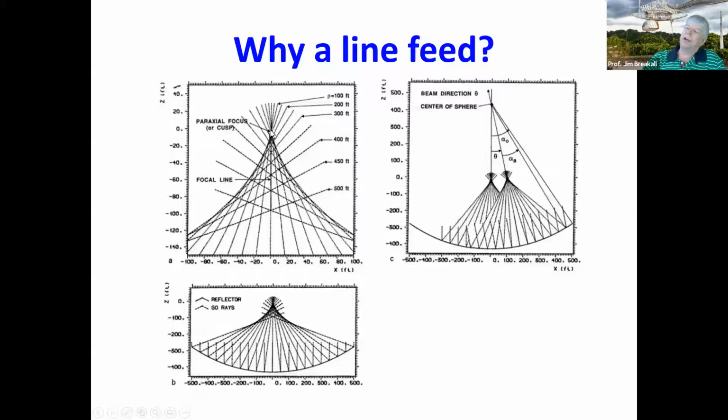So if we could put an antenna from this point down here, we could then collect all those rays, but they're coming in at different time delays. And so that's why the antenna has to have all those slots and different shapes to get this all back in focus again, where we can collect it up here at the feed point of that line feed.